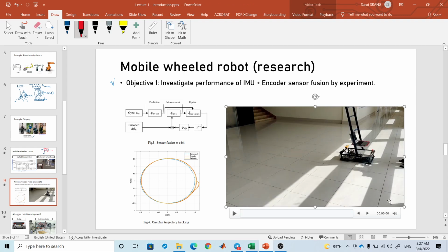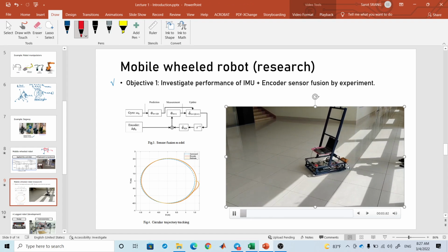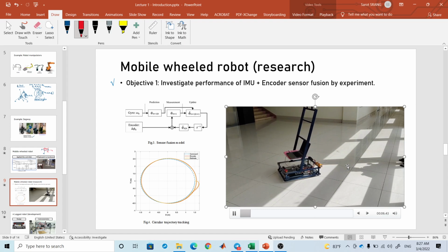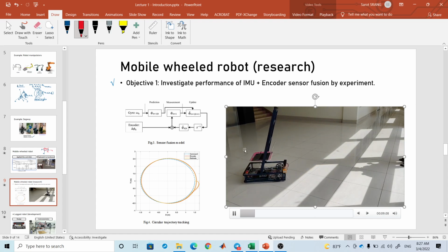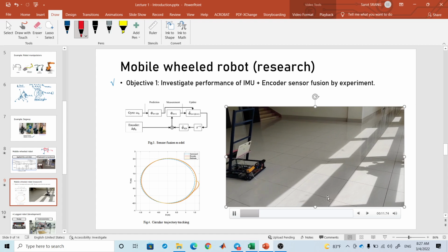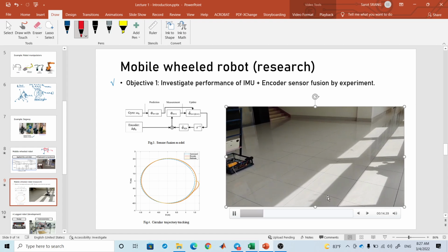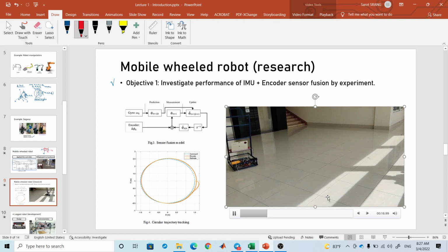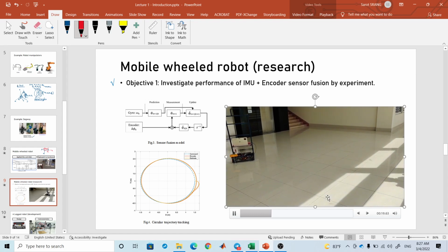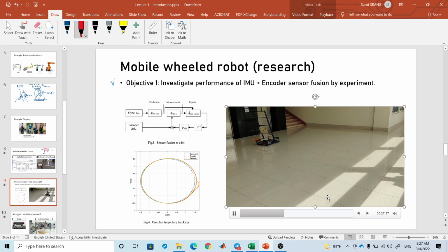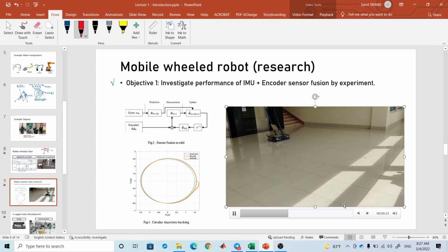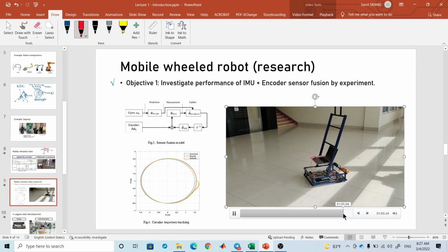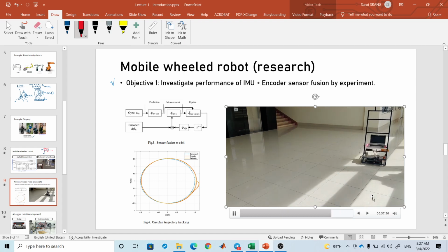When it detects the pen, in this robot we input the equation of a circle as a desired trajectory, and then we compute based on kinematics, and implement control theory to make the robot move along the trajectory that we input. So the equation of a circle, you can write it in terms of time. It's one round from there to here.